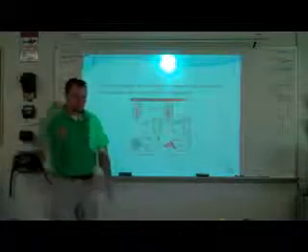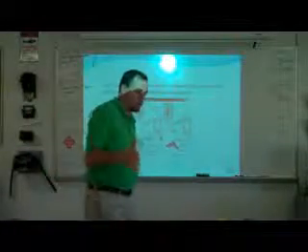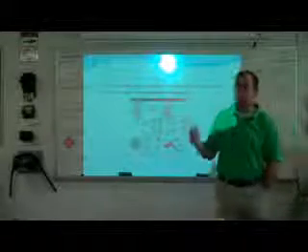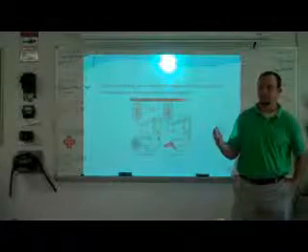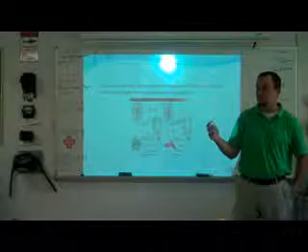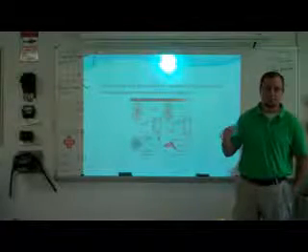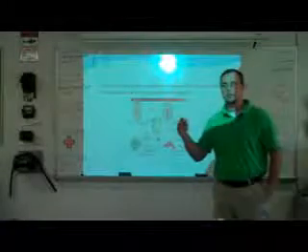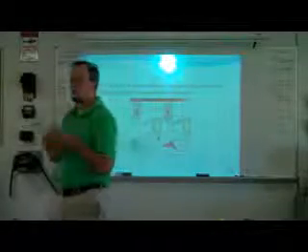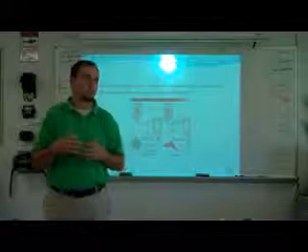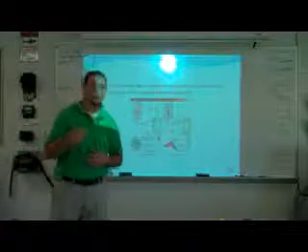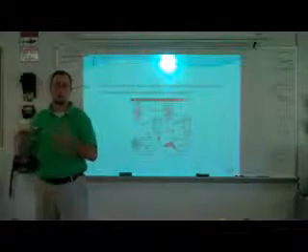Here's an easy example. My air conditioner in my doghouse normally pulls around 14 amps. And then we've got a light on that circuit and a couple little fans. This summer I didn't clean out the filters for a while, which starved that air conditioning unit for air. So it had to work harder to move the same amount of air and cool it down.